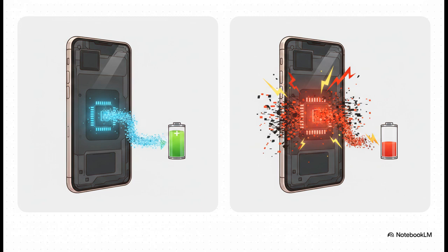And to tackle that battery life problem, we just can't rely on the phone's main processor to do all the heavy lifting. Video decoding is incredibly intensive work. So instead, we offload that task to specialized, dedicated hardware chips that are built right into the phone's silicon. These hardware decoders are orders of magnitude more power efficient than trying to do the same job in software.